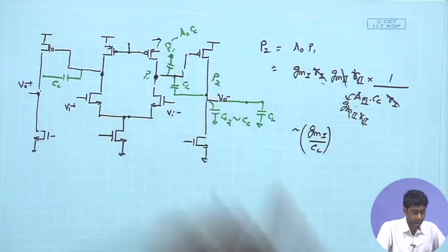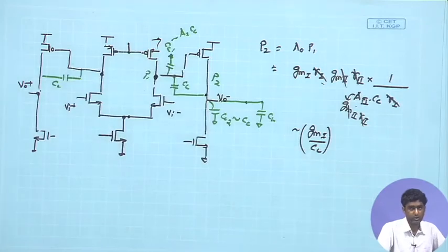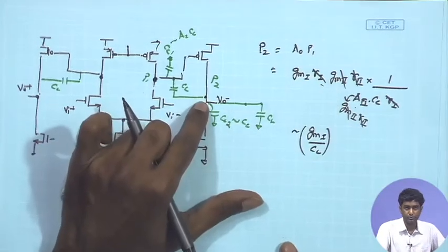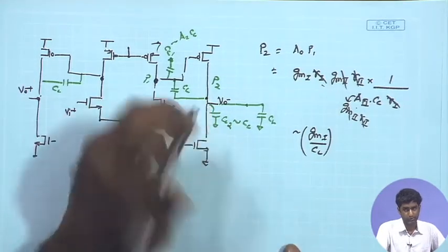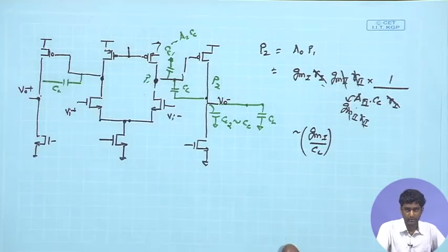Now, the other question is, what is the R equivalent at this point, that is what is the small signal resistance at this point. So, if I look at low frequencies, definitely for writing the gain we have used the overall R equivalent at this point equal to the RO of P parallel RO of N, that is giving us RO by 2.